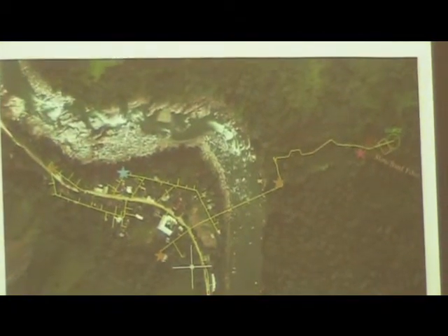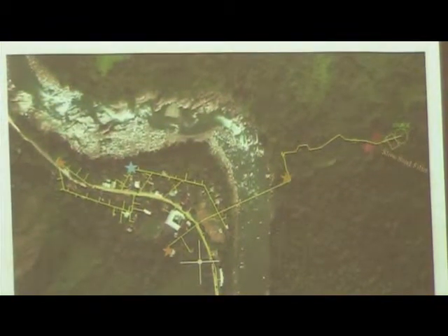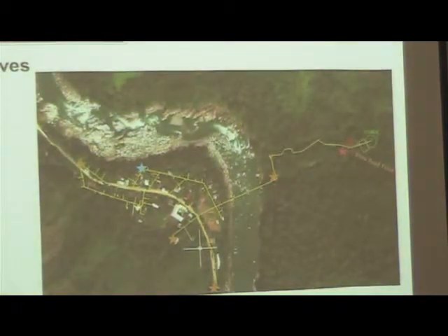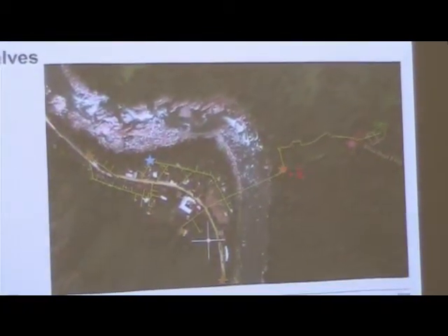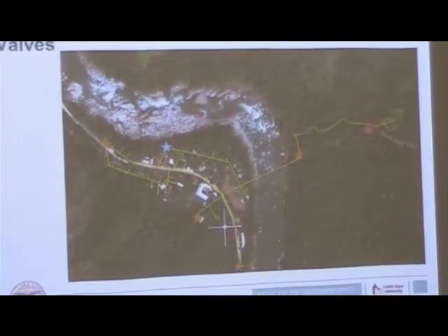This is another plan view. It shows where we're going to be placing valves in our system. We neglected valves in the minor loss calculations because, as you can see, there aren't very many. The orange stars represent air and vacuum release valves, and they're at high points in the system.